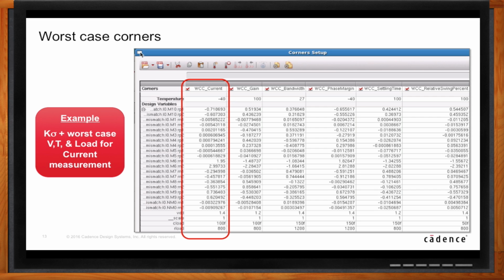And then last but not least is we can migrate designs. In that process, when you were working earlier, you were working at 65 nanometer, and you were then going to go down to 28 nanometer. And that's where we stepped in. We knew your designs just really needed to be scaled. Your layout, you're going to need to redo that. But the front-end designs, your topology was all the same, so we have an easy way of scaling that for you, and then recentering your design so that you're still meeting your specifications. And that takes out a lot of the trial and error.